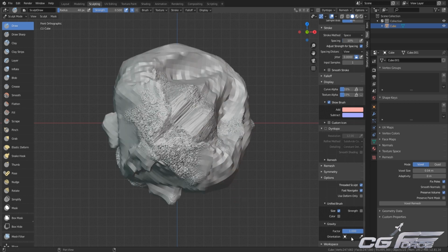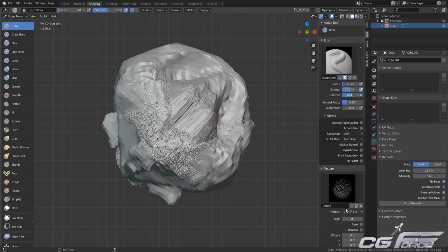Then we have this orientation, which is going to help you enlist your model in your orientation bar. Suppose you have rotated your sculpt model at some inclination angle in layout mode, and you enlist that model over here, it's simply going to use this z-axis as a gravitational axis to create that same influence which we are seeing over here. And now we are done with these properties.